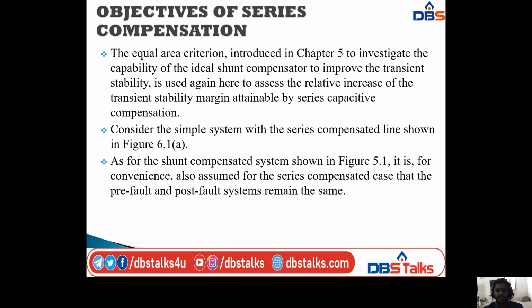In the previous concept, that is shunt compensation, we used the equal area criterion. The equal area criterion is used to give the maximum power capability in the system. It was introduced in shunt compensation to investigate the capability of the ideal shunt compensator to improve the transient stability.